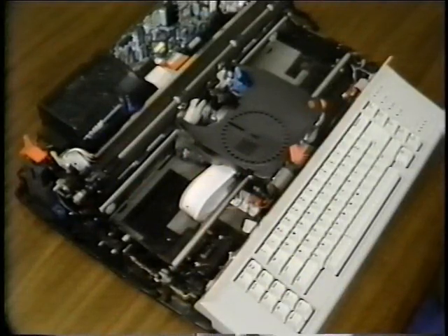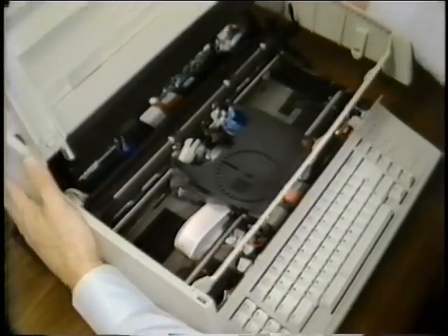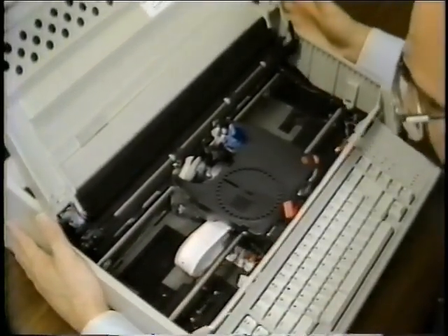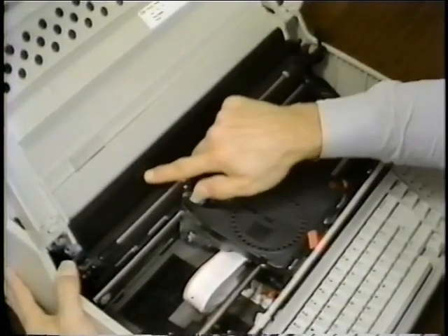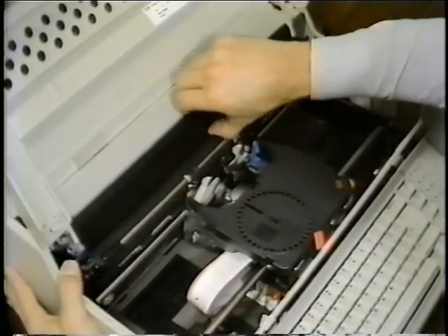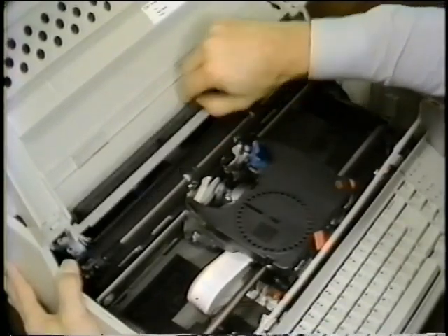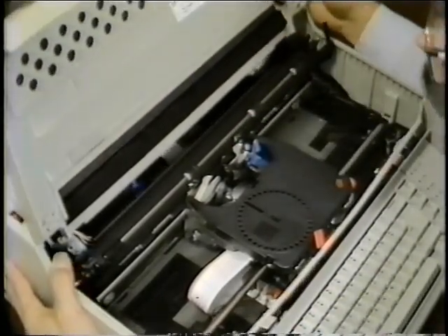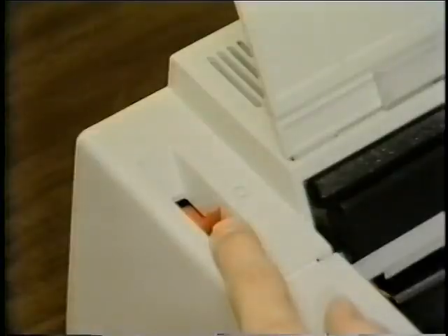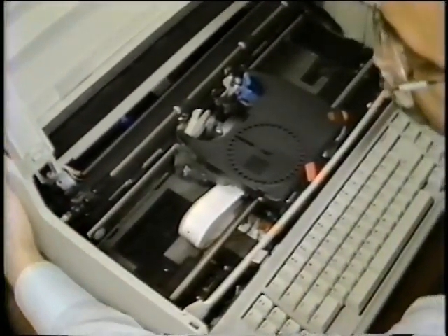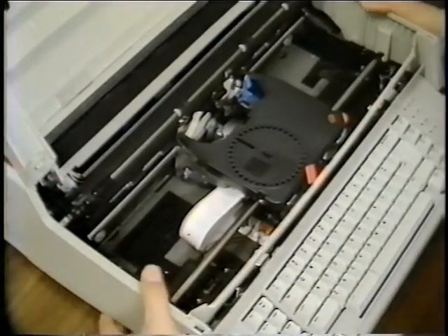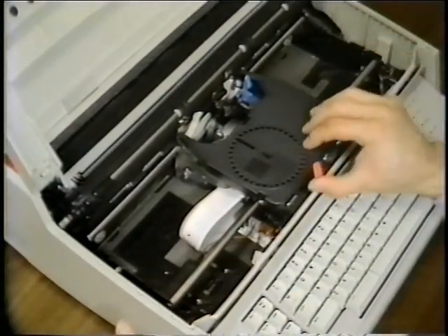First, place the cover on the machine so that the cover latches line up with the latching surfaces on the bottom cover. Next, rotate the erase table up so that it will not get trapped behind the platen when installing the cover. Be careful not to trap the on-off switch inside the cover. Finally, press down on the top cover above each of the latches until all four latches snap into place.